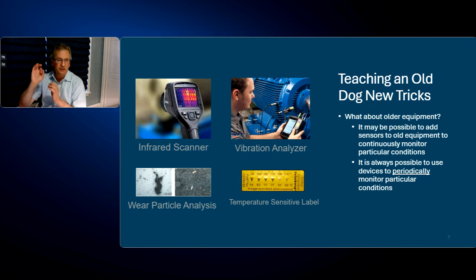We have set points that we put the probes on. So we're always very consistent there, measuring from the same points. And very importantly, as I'll mention later, we have to have a baseline. What is acceptable vibration, what is not acceptable vibration. But you would do this periodically. How frequently, I do not know. But you can do it periodically rather than continuously.